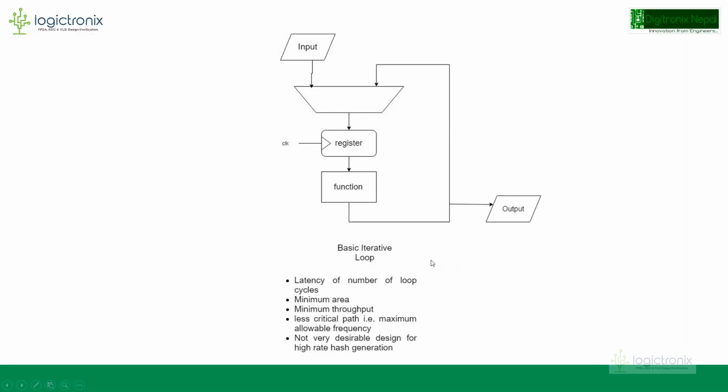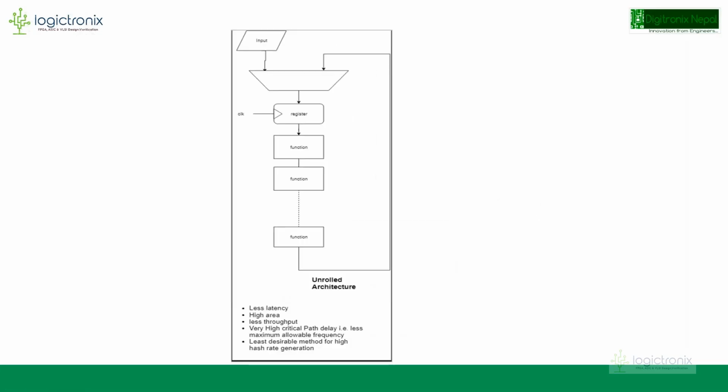So let's look at another design. In this case also we give input through this demux, and we pass it through the function, but this function is unrolled a number of times, like maybe 4 times or 8 times, or any number of times you want. You won't be able to stack this forever, but depending upon the function, you may be able to put this up to 8 times or 12 times, something like that.